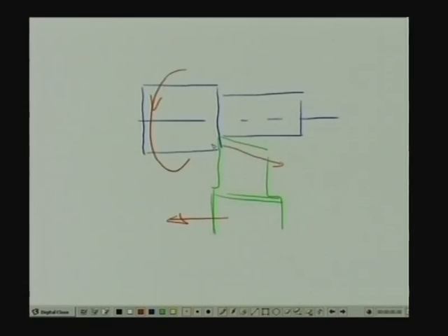If the work material is brittle, then the chips will be discontinuous, of irregular size and shape, small pieces, and they will automatically fall into the container at the bottom. But if the work material is ductile and the cutting tool has a positive or favorable rake, then the chip will flow continuously, and this will tend to go flat just like a sword.